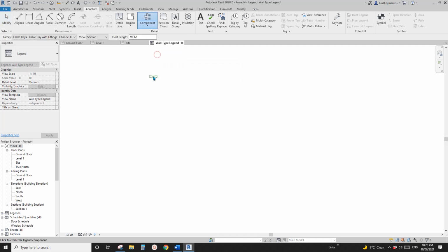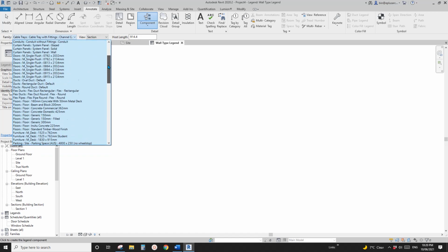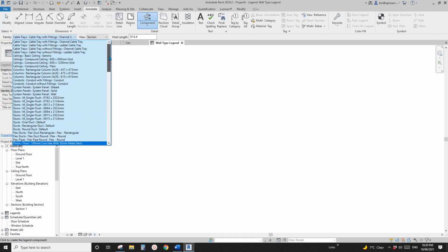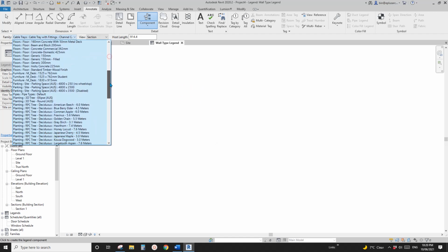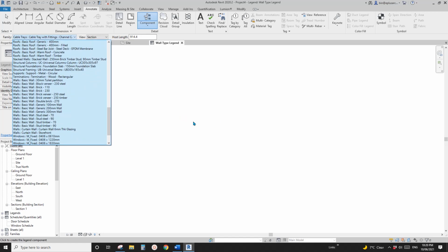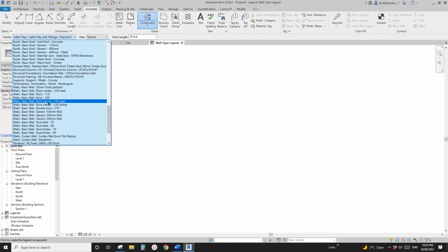Click on this, and then you will have this list. These are all the families, including system families and normal families, and you can pick them to place into this legend. For example, because this is a wall type legend, let's just pick some wall.